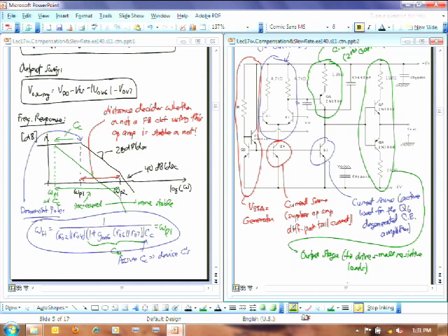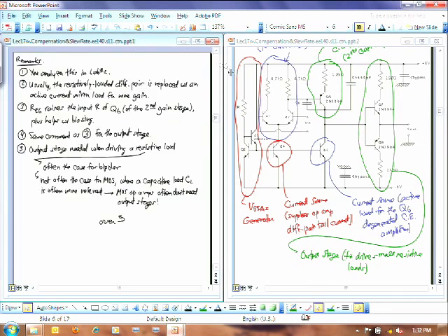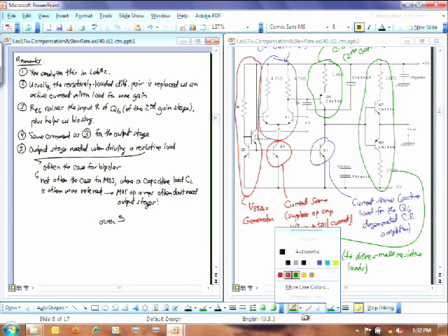So you analyzed this in lab number 2, so you all can recognize it. Usually, the resistively loaded differential pair, with these two resistors there, usually you put a current mirror there instead, right? You replace that with an active current mirror. So why is it you aren't doing that in your lab right now? It's because you're implementing this on a breadboard.